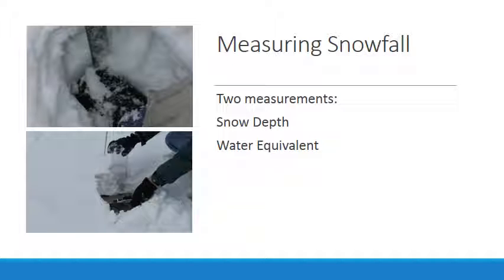Even when winds are light or moderate, the snow is drifting freely, and as a rule, it's best to take several measurements in an open place away from trees and obstructions, and then average them. To obtain the water equivalent, samples have to be melted and then weighed or measured as rain.